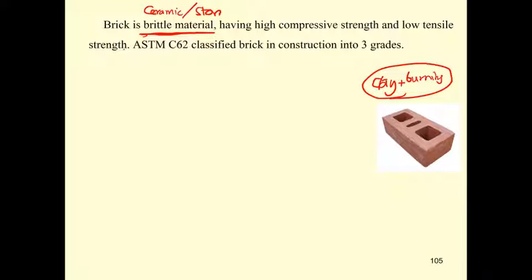The concrete has different materials: cement paste, sand, and crushed stone. When cracks occur, the stress can be distributed from one part to another part. For example, when the stress hits the stone, the stone can take care of the stress. So the behavior of the concrete is a ductile-like material. Anyway, it has very high strength, comparable to the stone. High compressive strength, but low tensile strength. That's typical for brittle materials such as cast iron also.